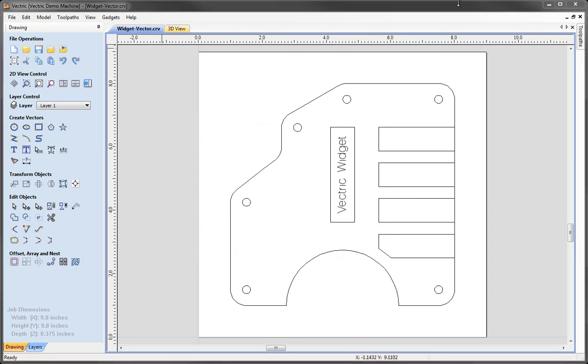In this tutorial, we've looked at a lot of different ways to create and edit vectors within the software. We started showing you how you could access the snap options, switch on the snap grid to help you sketch your vectors when using the creation tools. We looked at a number of ways that you can construct vectors, the trimming tools in order to trim them back to each other, how we can snap to things like the arc centers to create the drill holes that we've got here. We showed you subtracting one vector from another to create our semicircular shape.